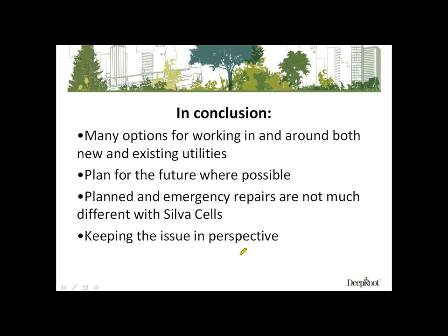you also have to keep the issue of Silva Cells and utilities in perspective. I know everyone thinks of, oh my God, it's a jungle of utilities, but if you think about it, and I'm not trying to diminish the importance and the conflicts that will arise, but also you have to remember there's thousands upon thousands of miles of utilities in every city, and Silva Cells are used commonly, but in comparison to how much utilities in the ground, your number of incidents of contact between Silva Cells and utilities are a fraction of that, and then of that fraction, that's where a leak or maintenance is going to occur.